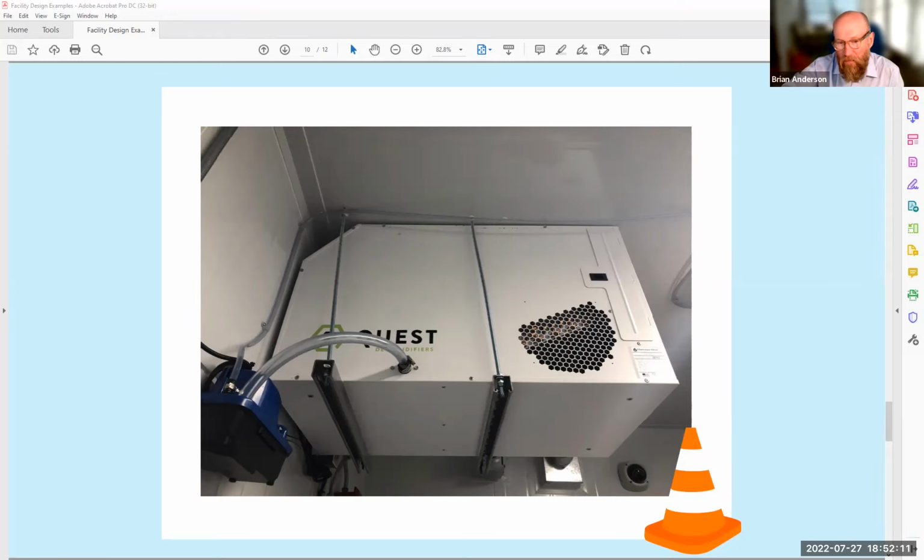So David's, where you started, I agree. Like the Unistrut clamps, those are hard to clean. That honeycomb grid, it's a cool design, but it's really hard to get the pathogens, any kind of cleaning instrument inside of that box. It just lets junk in when you don't want junk going. And that chamfered corner in the top, stuff gets up there. There's no way to clean that out. Usually you want to be able to at least get your hand in with a sanitizing rag on top of that box, and there's not enough clearance between that and the ceiling. So you've got this uncleanable, very large surface.